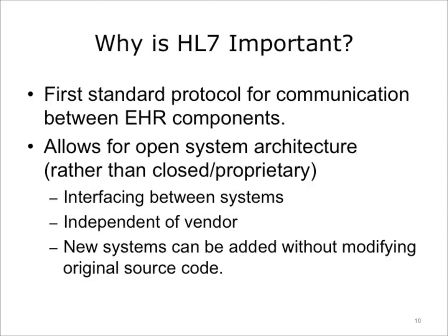Closed or proprietary system coding is generally hidden by the vendor and promotes reliance on single vendors and specific applications and technologies to remain operational. Following a standard protocol, however, provides you the advantage of being able to connect to any system that supports this particular part of the standard, both now and in the future. Adhering to a standard protocol is called open system architecture. Open system architecture allows interfacing between systems using appropriate protocols, independent of vendor.